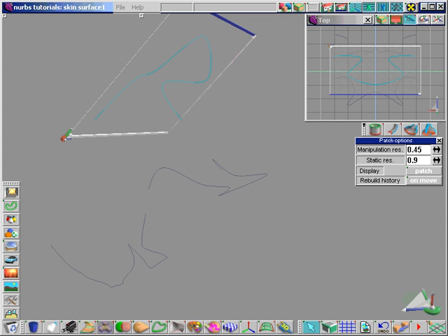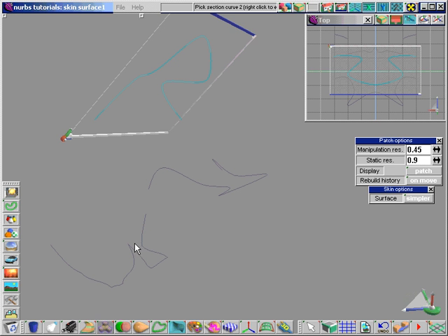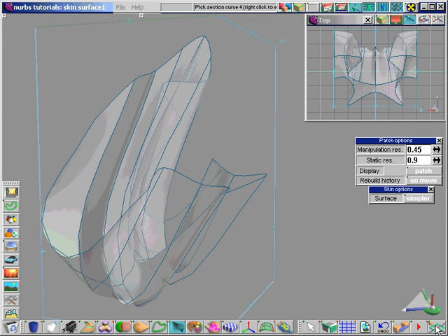The patch options were covered in a separate tutorial. You can view the patch mesh or both, and you can control the level of detail shown in the real-time display. When you first start skinning curves, you'll probably set them up in a linear sequence, as in constructing a boat hull or character limb. There's a lot more power in visualizing the surface created when skinning out of order. Experiment and you'll get used to anticipating the resulting surface.